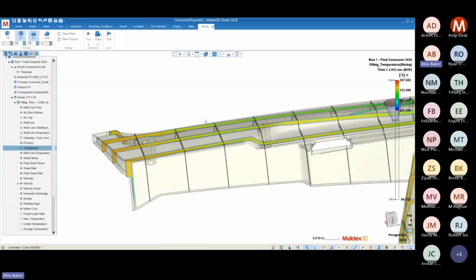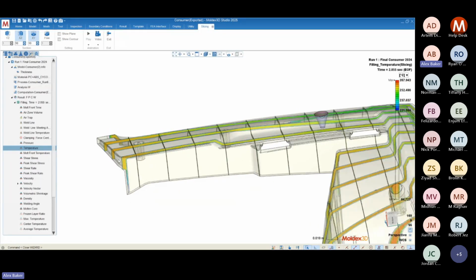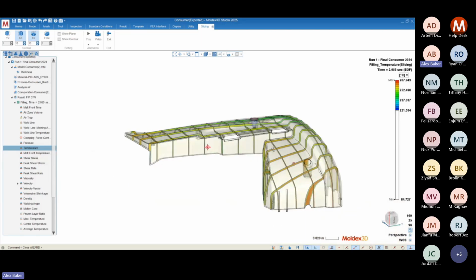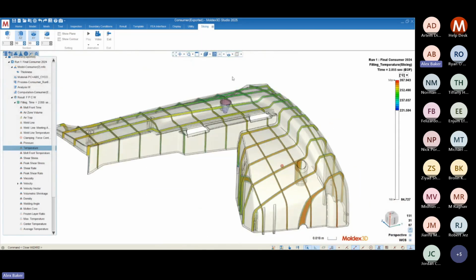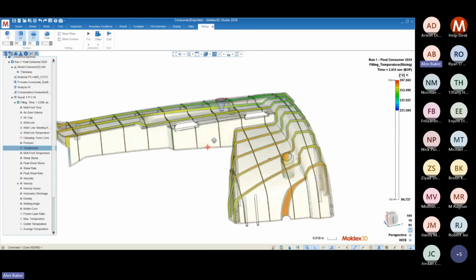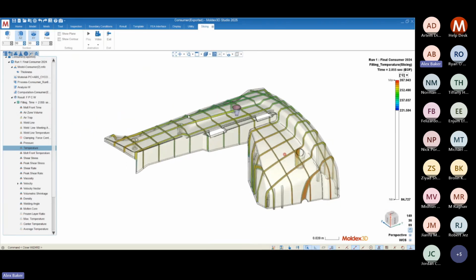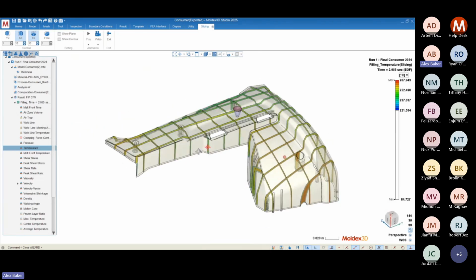All right, so the area out here, the hotter material, is going to be at a higher shrinkage rate. So this area at the end of fill is going to shrink more than the gate location, and that can result in warpage by itself. This is an effect that's very important to take a look at. And this, what I call the slicing grid, is the best methodology to be able to visualize this temperature variation through our geometry.